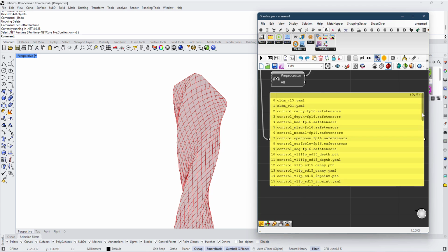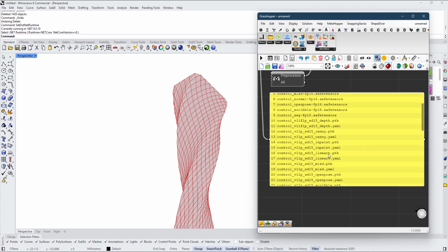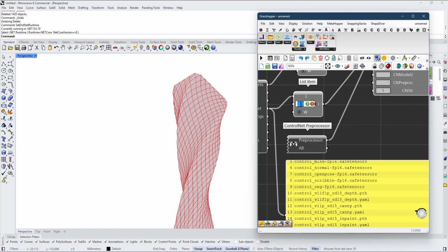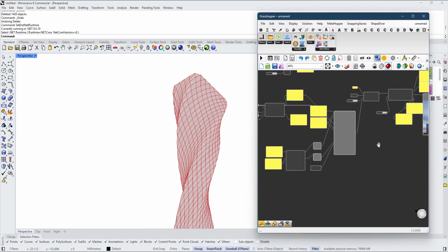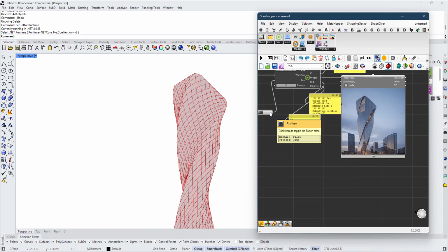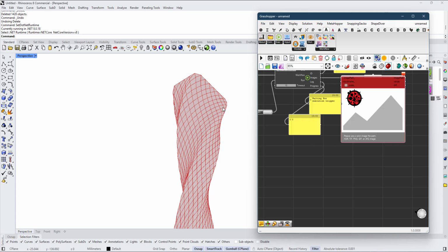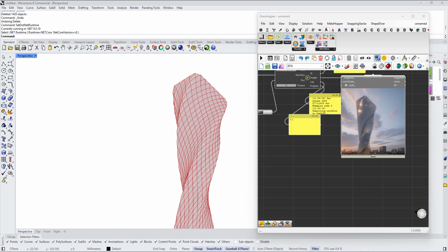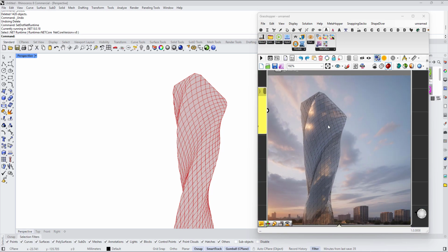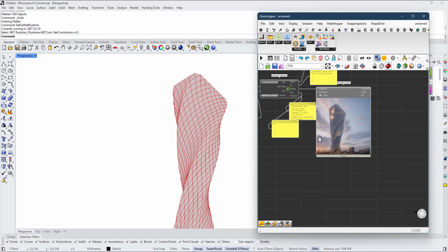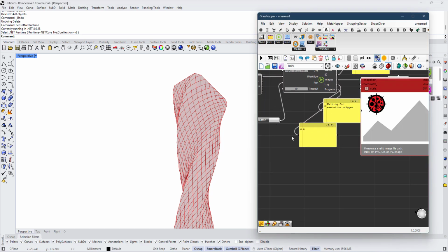So line art has the index which is 16, so I'm going to pick 16 here, and that will be my control net model, which is line art, right? Now I'm going to run again, but this time, instead of using depth, it will use the line art and will give me those details of facades and so on. Yeah. So here, as we see, we have this diamond shape of the facade. I think this is better than what we got before.